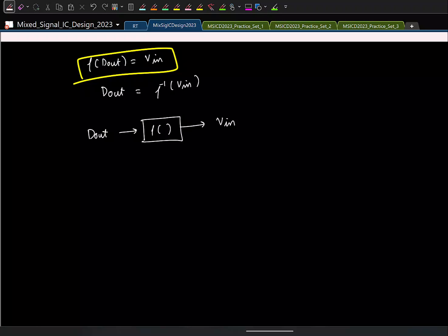So what we have to do is this. So let us say it's a 3-bit DAC, right? So we'll get B3, B2, B1. Nominally we reconstruct the output as this 4B3 plus 2B2 plus B1. This is a linear reconstruction. Now we no longer should be doing this. We should be doing it in a nonlinear fashion, and that simply boils down to the fact that I'll have to have some K3 times B3.